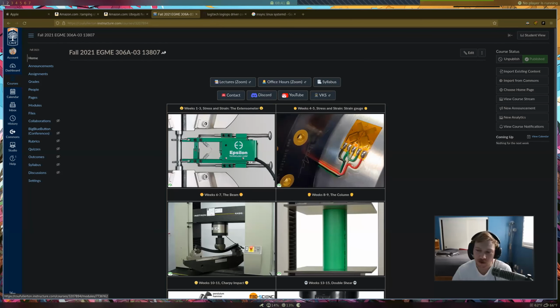So the strain gauge, it's applied directly to the rod that you're testing. And since it's directly applied to it, we're not going to break the rod because, well, now we got to get a new strain gauge and apply it to a new rod. That's a lot of work. So we're going to apply it to a rod, and once we actually run the test next week, we're not going to break it. So we're going to just load it to where it's still within the elastic range for our rod. I think it's aluminum 6061-T6 again, and we only have one material this time.